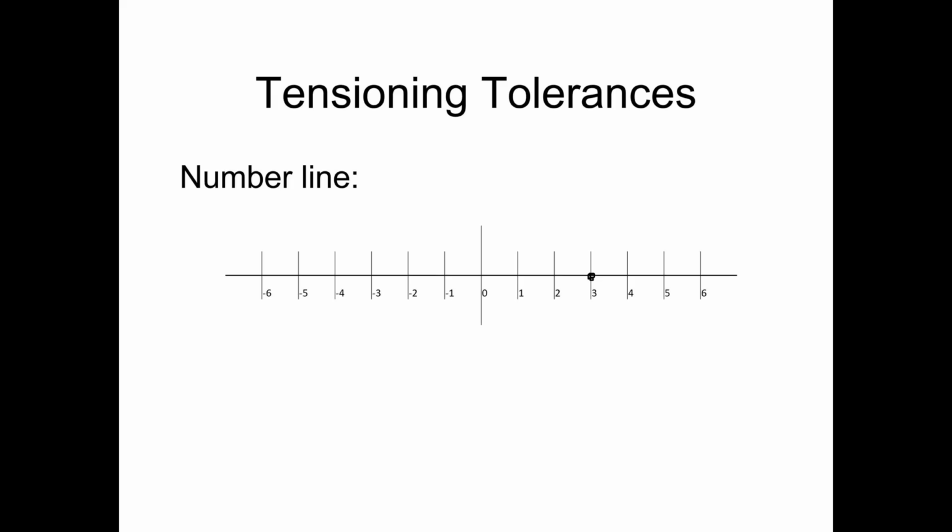So force is 3% over, elongation is 2% over. So right here's our elongation. Force was applied within 5%, elongation was within plus or minus 5%. So now let's ask our third question. Is the combined within 5%? In this case, the combined error in force and elongation is only 1%. So yes, this strand was tensioned in tolerance.